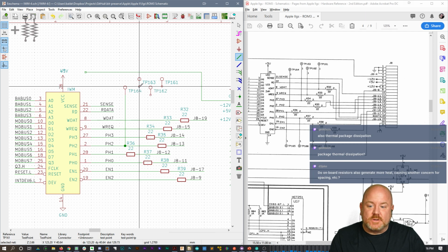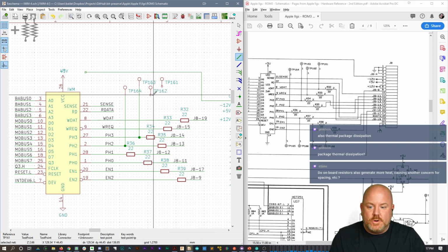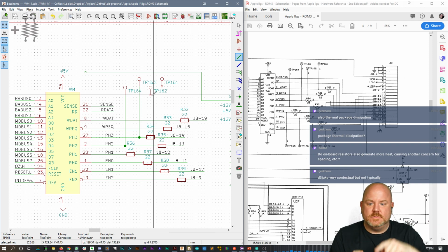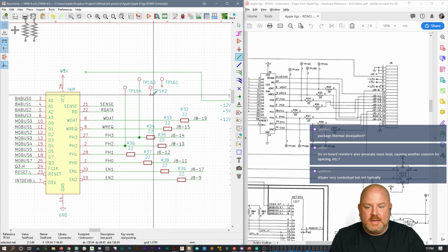Now, here's the cool thing, and if I had a picture of it, I would show it to you, but I'd have to go find it. You don't normally actually put a resistor into an IC. Sometimes you'll see these zigzag patterns on the die, and that could be a resistor, usually if they want to laser trim it to a certain value.